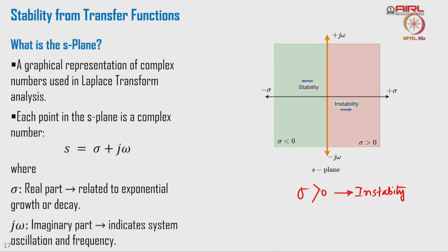So, the system poles, when we plot, the right hand plane is this, and this is called left hand plane. We do not want the poles of the systems to be on the right hand plane. This is something which we do not want. The poles, which we denote by this small cross sign, should be ideally at the left half plane, and that gives a stable response. Right half plane is a region of instability.